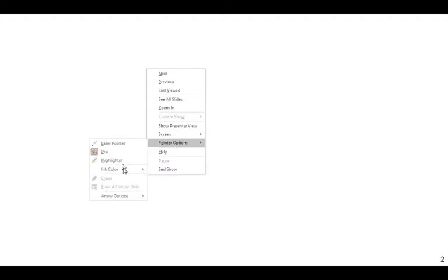Okay, so what I want to do is a long form example demonstrating how we actually solve for this. So let's look at calculating an interaction diagram. I want to describe a section and then find 5 critical points, and once I have those 5 points, I'll use them to define my interaction diagram.